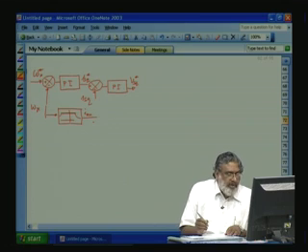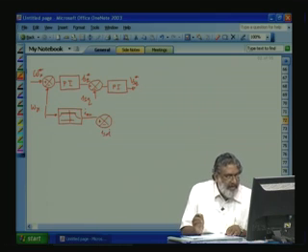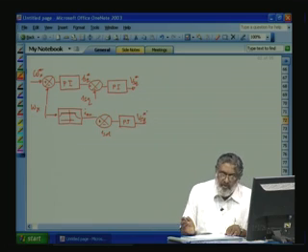During steady state of operation, IMR will be equal to ISD. So, we have the ISD feedback here, ISD. This is the PI controller. This will give you our VSD star.